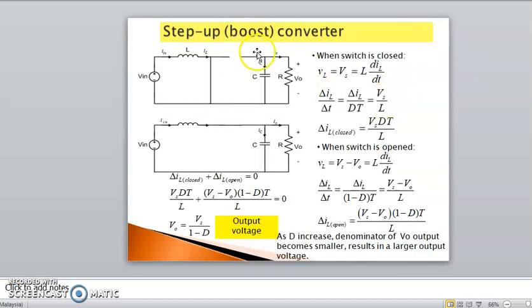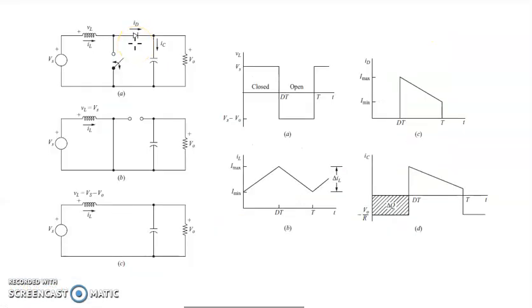So this is the assumption that we make for the step up DC boost converter. We take a look at the circuit in the on state and off state, at the topology and the behavior and response of the circuit. Then we go into the formulas and equations. Assume now that S2 is a diode and S1 is a switch, might be a MOSFET or whatever. So far we consider it as a manual switch.